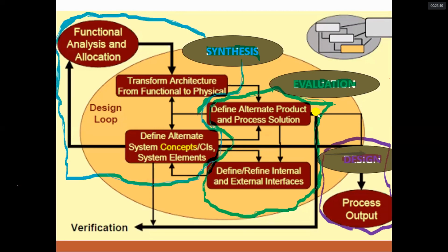We have two types of drawings: one is presentation drawing and the other is working drawing. In presentation drawings, we have rendered plans. Rendered plans are just colored plans with textures, without detailed dimensioning, just a set of areas and peripheral dimensions. When your presentation plan is accepted, then your working plan, which will actually be executed, is your dimensional plan. It gives the dimensions and detail of each and every feature in your floor plan.